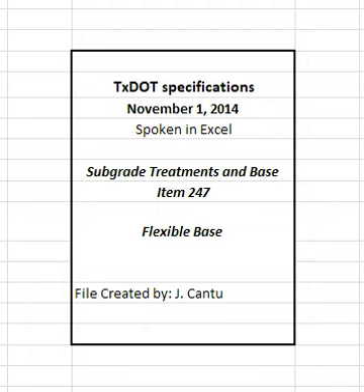Manipulate and thoroughly mix the new base with existing material to provide a uniform mixture to the specified depth before shaping. Proof roll the roadbed in accordance with Item 216, proof rolling, before pulverizing or scarifying when shown on the plans or directed. Correct soft spots as directed. 4.2 Placing. Spread and shape flexible base into a uniform layer with an approved spreader the same day as delivered unless otherwise approved. Construct layers to the thickness shown on the plans.